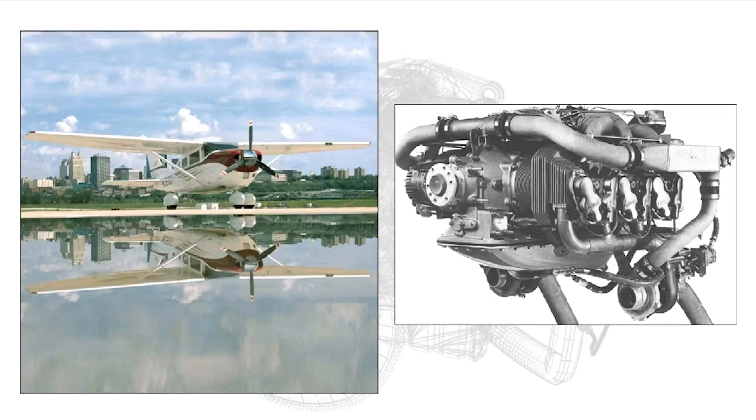Where a supercharger is used to increase the engine power output at sea level, rather than to maintain normal engine power output up to a high altitude, the engine will need to be strengthened in order to resist the high combustion pressure. This type of engine, like the one shown here, is fitted with what is called a ground-boosted supercharger.